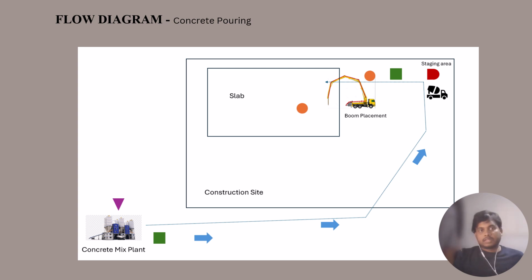A significant issue identified in this diagram is the queuing of trucks at the staging area. This delay led to downtime at the pump and impacted the continuity of concrete placement.